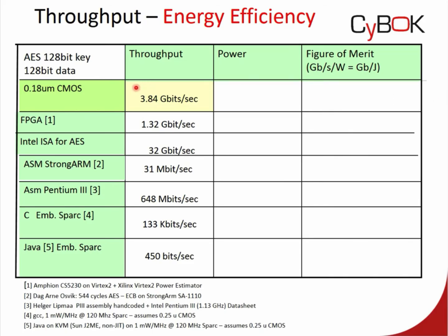The first was this ASIC chip that I showed you. It's dedicated to encrypting AES, and it reaches 3.85 gigabits per second at a cost of 350 milliwatts. On FPGA, we can also implement AES. It gets you slightly lower gigabits per second because this is a programmable platform. It's not a dedicated platform, but still at very good quality, with power consumption of close to 500 milliwatts.